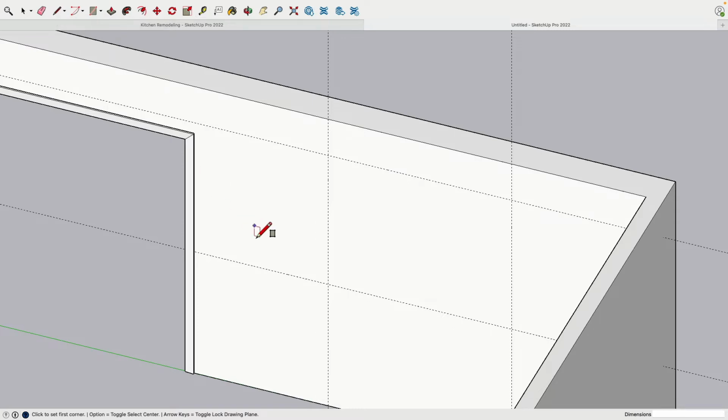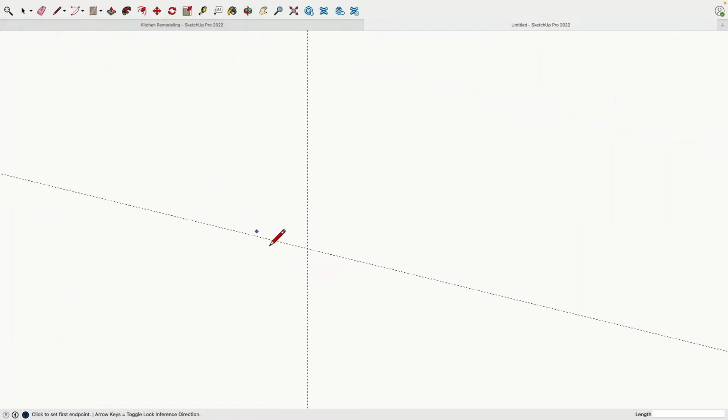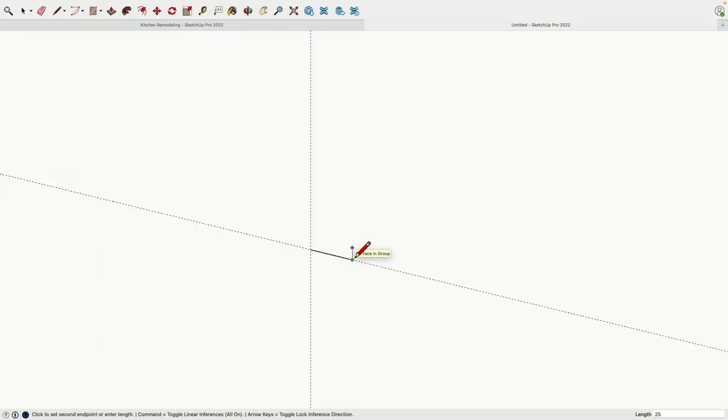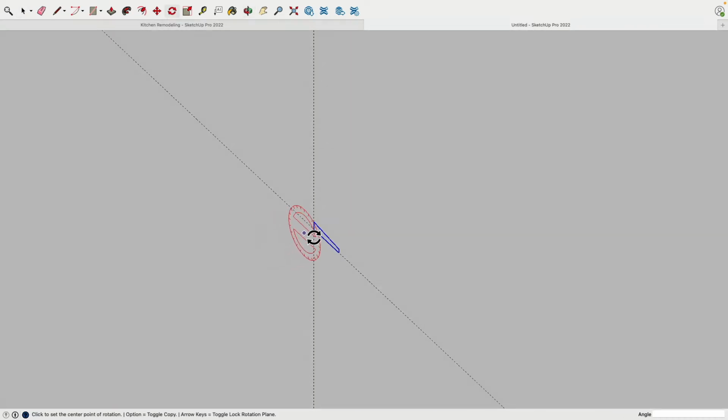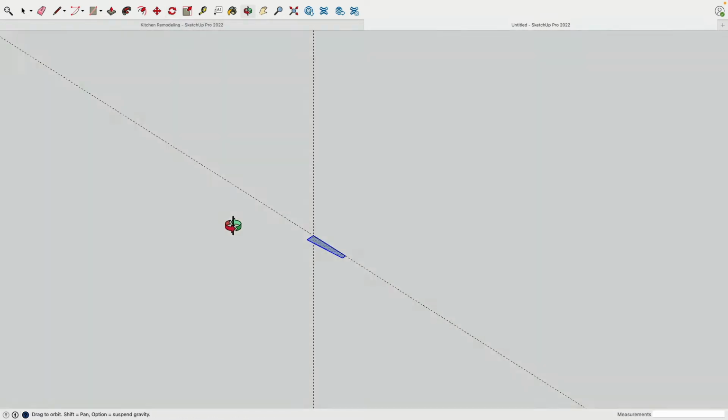So here now we will do the same. Let's quickly draw the trim. So 2.5 inches. And this is the inside, 0.25. Escape from here along the z-axis, 0.5. And then we can connect this. Very good. This whole shebang we're going to rotate now. Yeah, we need to switch the orientation. For the rotation tool, I press the left arrow key there, click, click, click. There we are. Very nice.